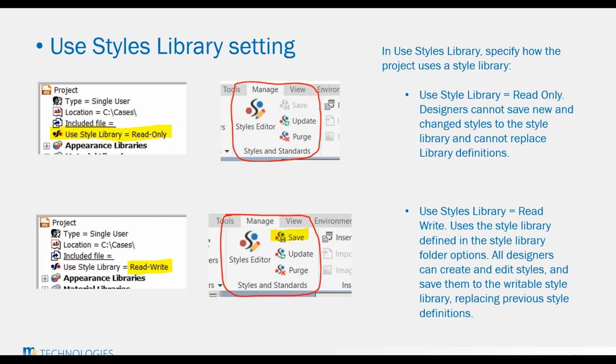The design data is nothing more than a bunch of XML files that hold these settings for the different areas that you're in. For a part file, you can only change the lighting and the text, because you have 3D annotations that you can now put on the part files. But for the DWGs and the IDWs, there's a lot more information that the design data stores. For example, your call-out balloon information, your dimensioning information, whether it's 2 or 4 places with tolerances. All that is captured and saved in XML files. Same with layers, parts list, and so on.